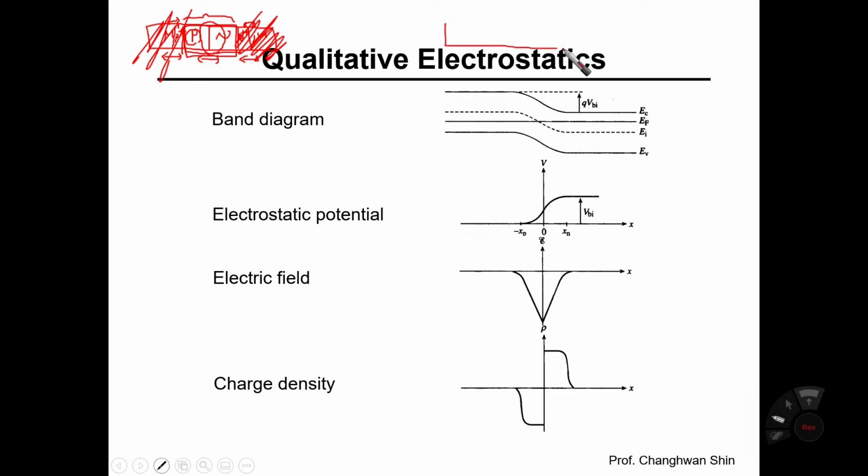So herein, you're going to see P and N. Usually the N side is grounded or referenced, so the voltage difference across the PN junction diode is denoted as V sub A, the applied voltage, which is positive on the P side, and the N side is negative, usually 0 volts. The positive current direction is defined as the current flow from P to N.